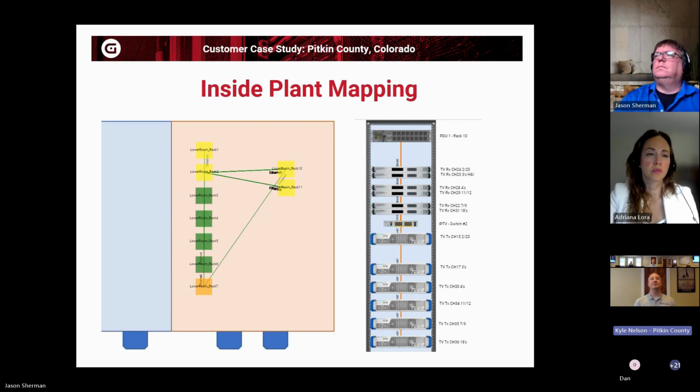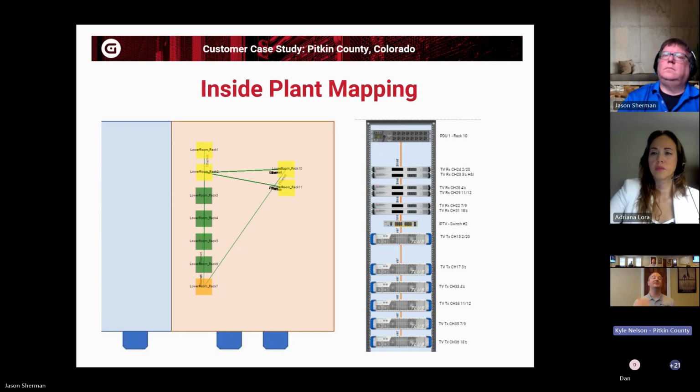And being able to also document, you see at the top of the rack, we have our PDU or power distribution unit. And from there, we actually have documented down to which unit or which device connects to which port on that PDU, so that if we have to remotely power cycle one of those via these Ethernet capable PDUs, we're able to do that and quickly know what device, what port we should be looking for.